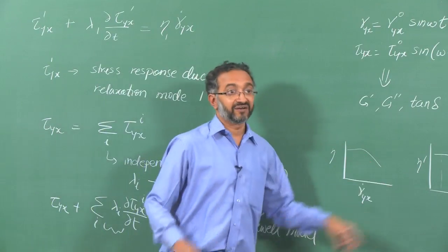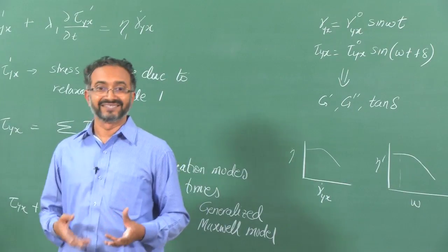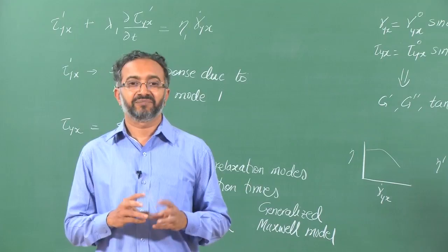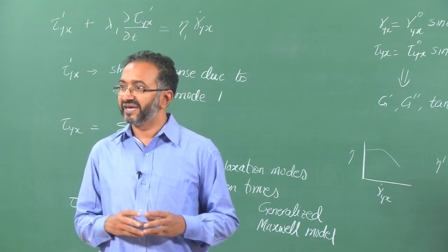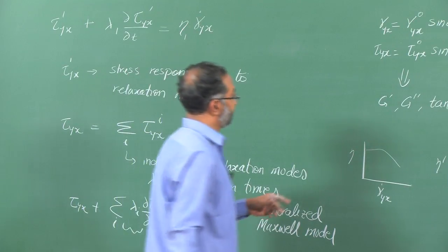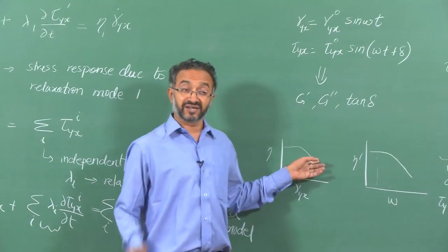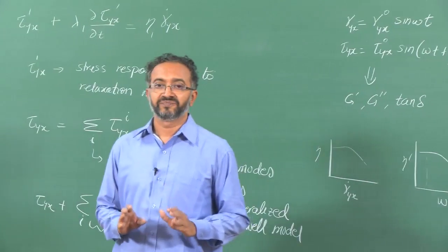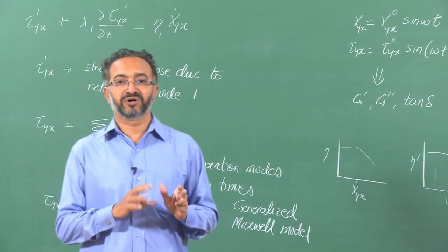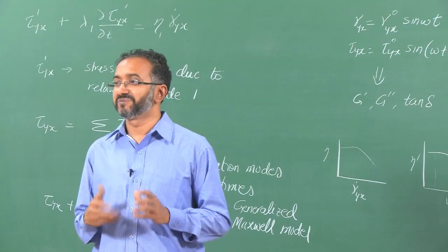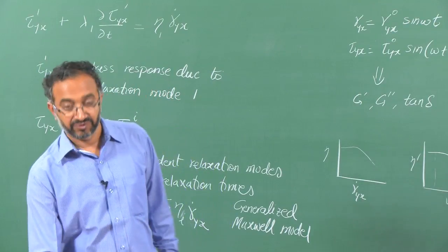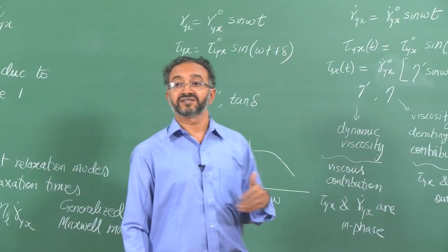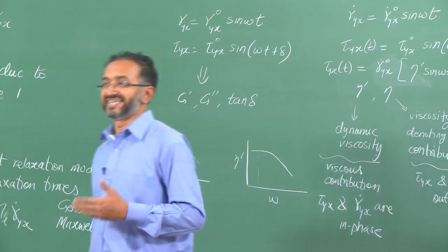And as we saw, in making the material shear thinning, of course there are elastic mechanisms, the fact that a macromolecule can orient or the fact that particles can agglomerate and break. So those kinds of features are present which can lead to shear thinning, but when we do a steady shear experiment we are only characterizing the steady response and therefore only the viscous response of the material. So is there a correspondence between these two, and does it make sense?